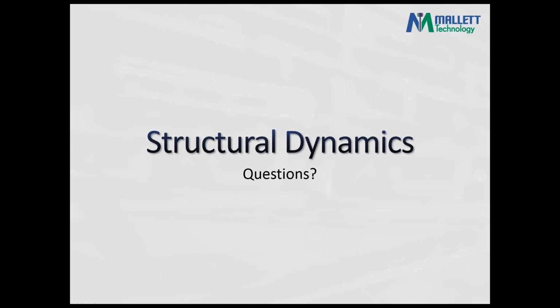Anyone? Well, one thing that I would add, I suppose, would be to say that modal analysis, as Steve mentioned, gives us a lot of great insight as to how a structure could potentially respond to an input. But to get a deterministic result, be it a displacement or a stress, we need to characterize the input, the excitation, the load. So you first do modal to see what might happen at any given frequency, but you need to know the mode.